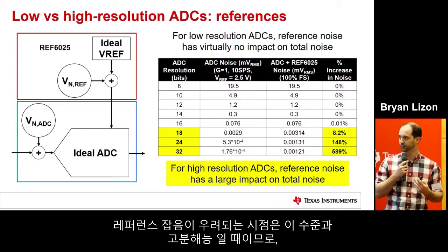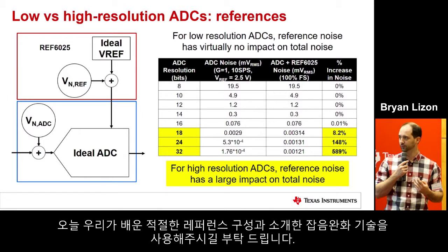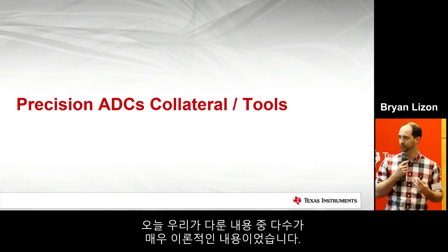It's really at the high resolution level where you need to be concerned about reference noise and making sure that you're following the guidelines presented today, using the appropriate reference configuration, and using the other noise mitigation techniques.